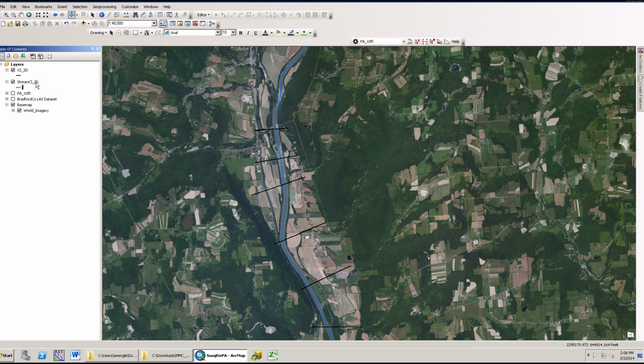If there is a line layer in the current map document and the user is not in an ArcMap editing session, the Identify Measure Elevation tool will be active to use. Additionally, in order for this tool to work, the map data frame and line layer must have a coordinate system defined with vertical and horizontal units in US feet.